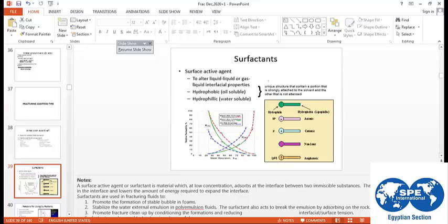Once you break the formation, if you start pumping at 5 barrels per minute, or 10 barrels per minute, and keep this rate constant, the treating pressure during the frac job will increase gradually up to a certain point, then will start to increase sharply. This highest point in the data frac is the fracture point. You can calculate the frac gradient from this point.